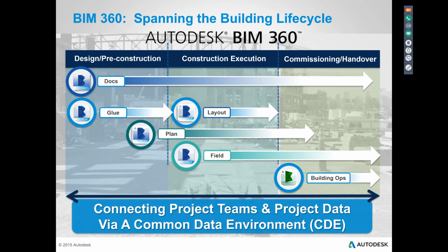And in fact, hopefully I get a chance to show you a couple of really cool things here today about that. And I meant to have a website already dialed up, but I'll show you some cool things that you can do with Glue now with some of the new functionality. So that tool is using the Navisworks Clash engine via the cloud. Currently today, you upload your models to the Glue site, and then you can perform merged model operations, and you can do clash detection and markups there as well.